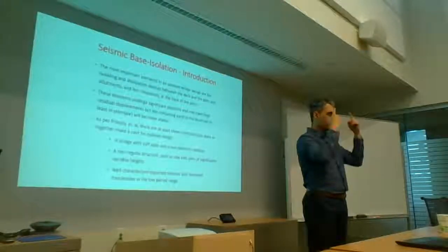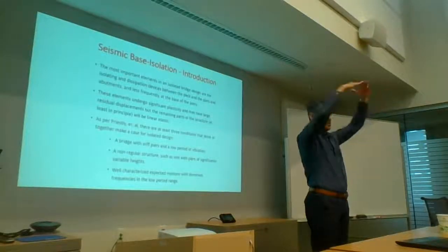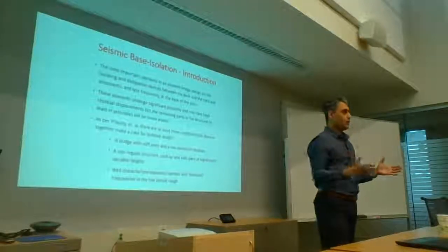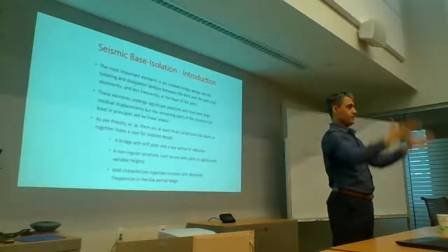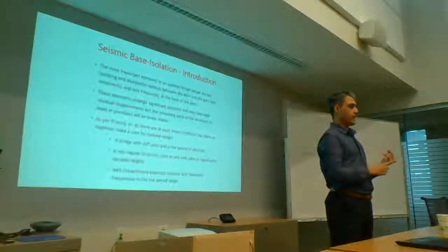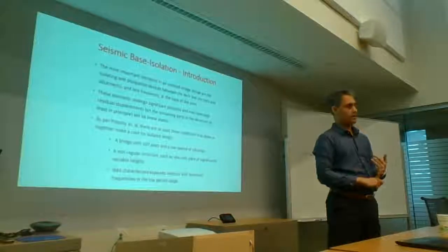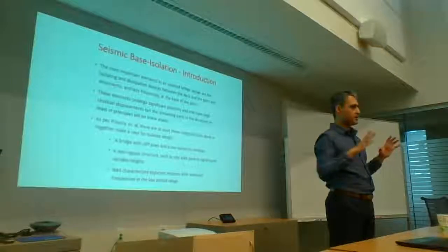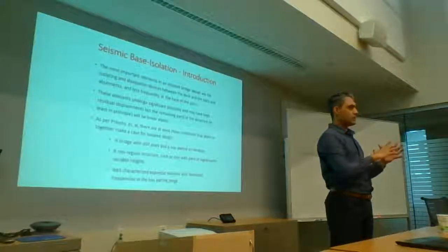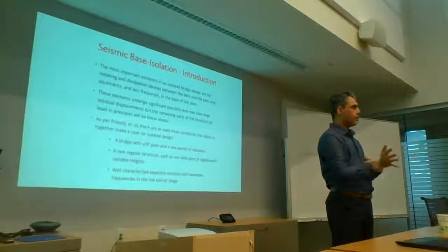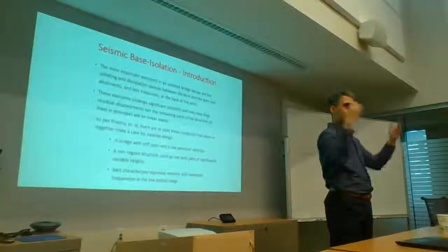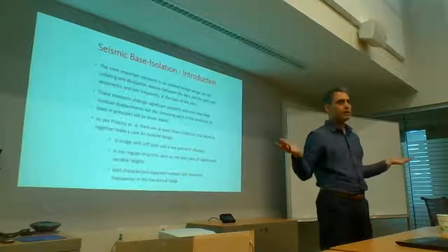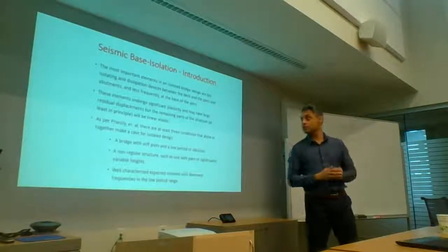Usually, when you think of buildings and bridges, you know that your seismic mass is up there. It's in the floor. It's in the deck. Now here, all the seismic mass is in this ginormous, big, strong wall with bad mortar and unshaped masonry. It's really bad, and the trusses are just not able to stabilize those things. So these are pretty much freestanding walls. So these walls basically crumbled under their own inertia, and the roofs fell down. It's not that the roofs brought down the walls; it's just that the walls crumbled and killed thousands of children, and that was quite heartrending.